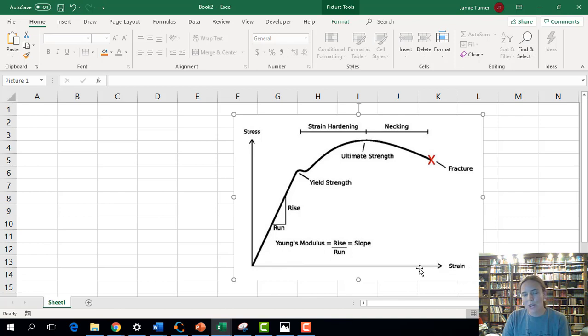So you'd have a lot of strain, a lot of stretching with very little force for a ductile material, and then somewhere in between. And you don't want a brittle failure. Brittle materials tend to be stronger, but that comes at the expense of you don't have any warning when the thing is going to break. So all of a sudden it cracks and you have a disaster.